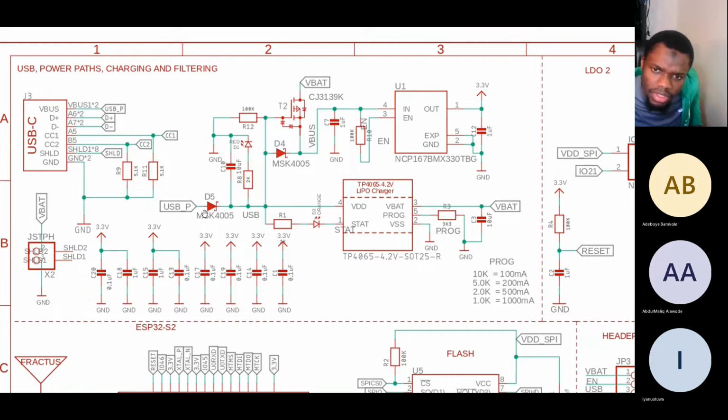Do you know what Schottky diodes are? I'm sure you know what diodes are, but maybe you've not heard about Schottky diodes or you've not used them before. Schottky diodes are low voltage drop diodes. They still do what normal diodes do, but they have a lower voltage drop. A typical diode takes out about 0.7 volts, which reduces the voltage you have at the end.